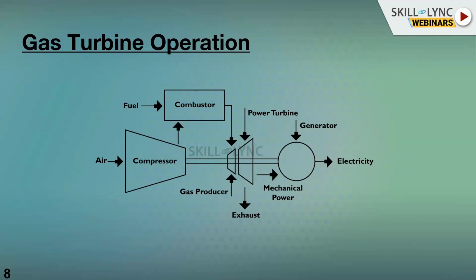So instead of letting it go to waste, a lot of power plant owners put in an HRSG, a heat recovery steam generator, which is basically a normal heat exchanger. They take the hot air from the gas turbine exhaust and use it to produce steam to run the steam turbine. That's it. So that is one use of the exhaust gases from a gas turbine.